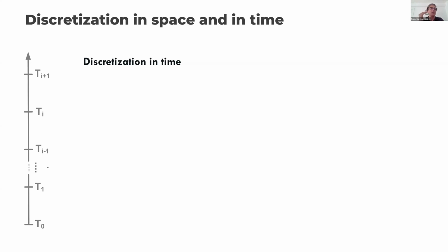You see, there is no sense talking about some instant between two time steps. Okay, so the time is also discrete, and we discretize the equations in space and also discretize the equations in time. Okay, and in terms of time, the equations or the methods can be explicit. So probably you will have already heard about these names.